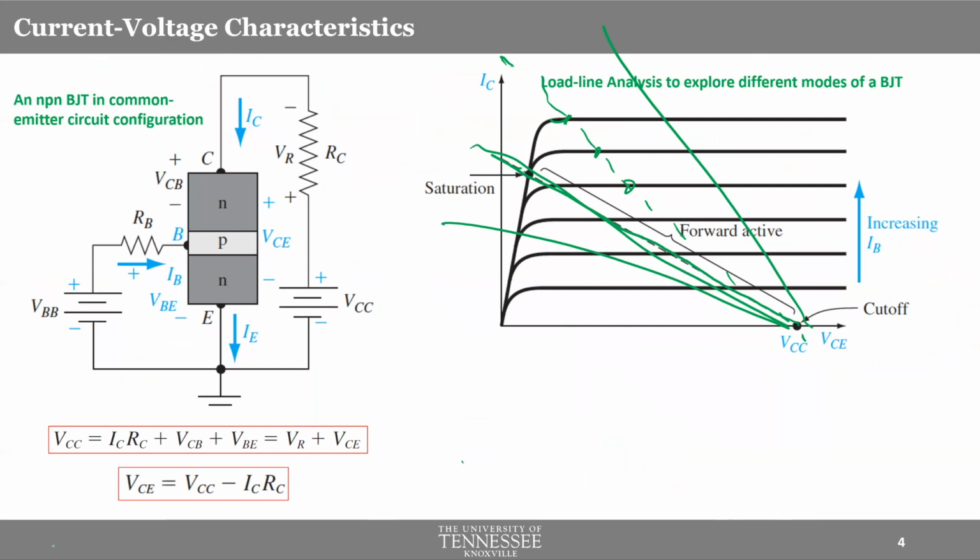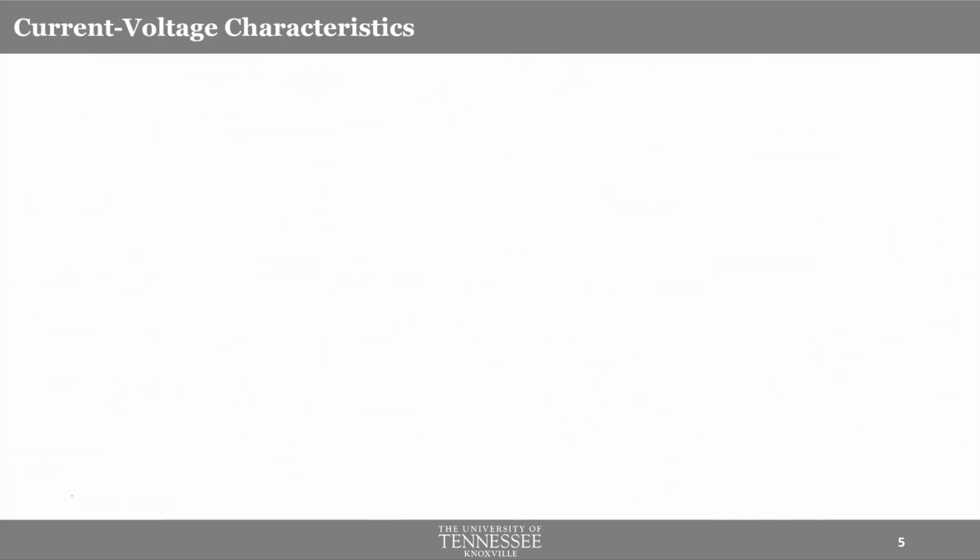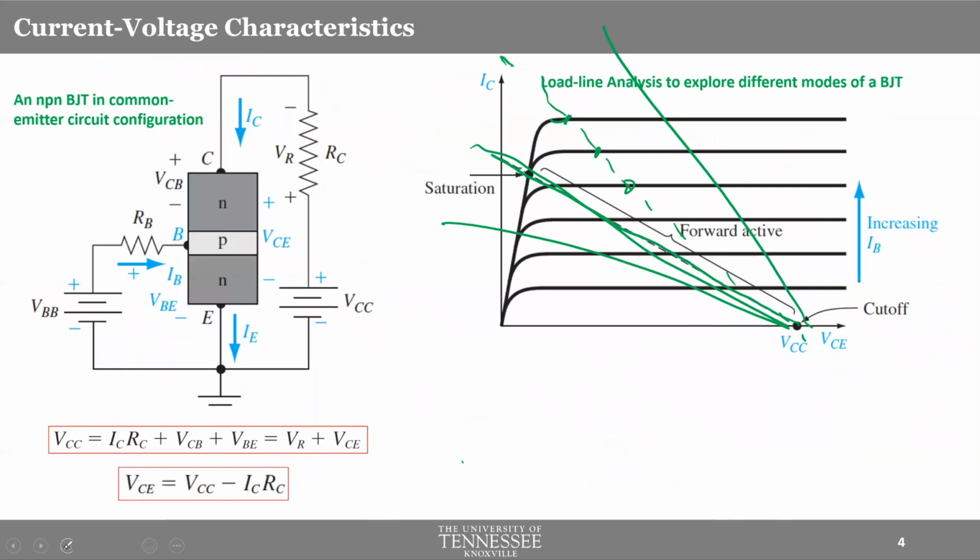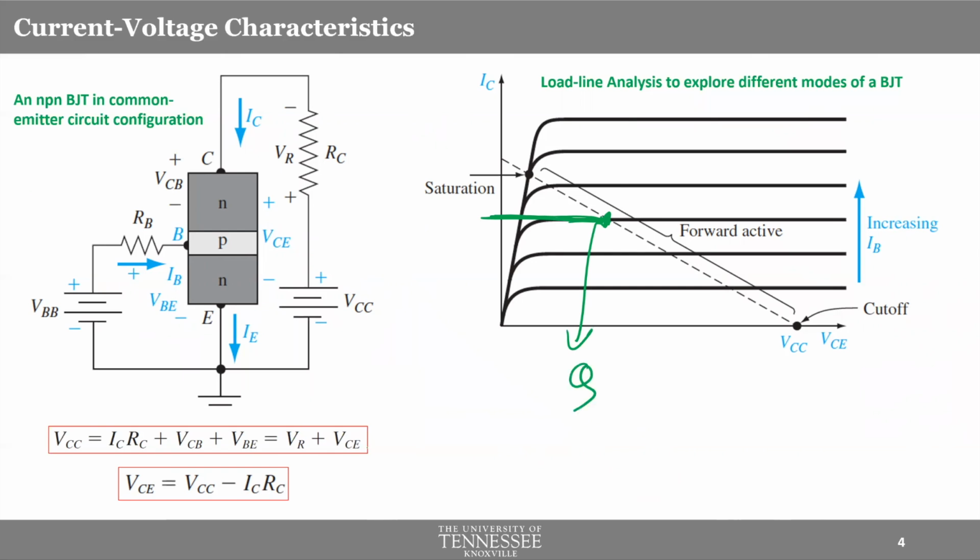Now, before we conclude, by the way, the line that we have drawn, the straight line, this is famously known as the load line. And you might have seen, you might have hopefully understood, that the point of intersection is a very important point, because that dictates the overall solution for the system. Okay, so this much will be the final collector current, done. Now this point is usually mentioned as Q point. Okay, Q point. This is a famous popular notation that people use.